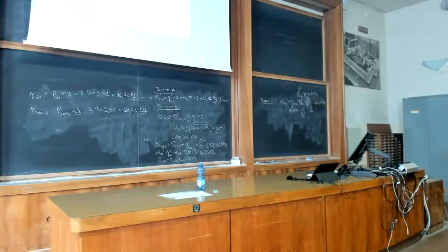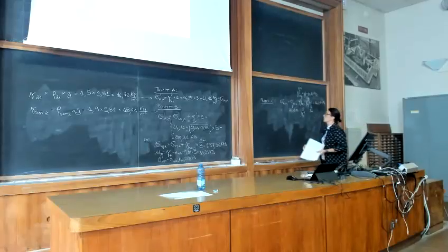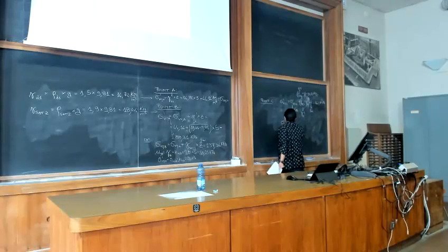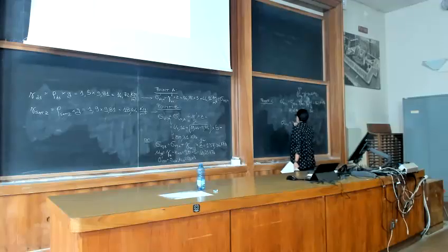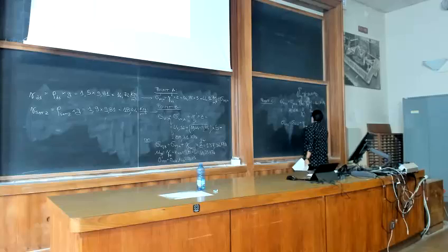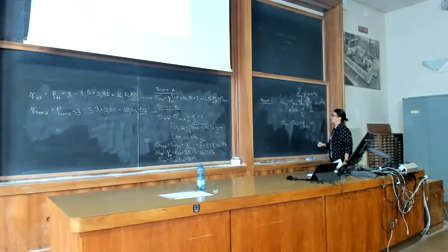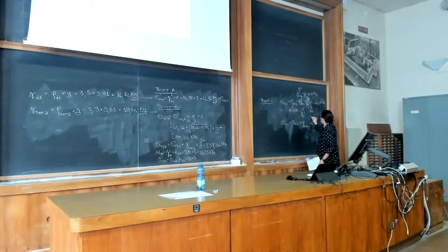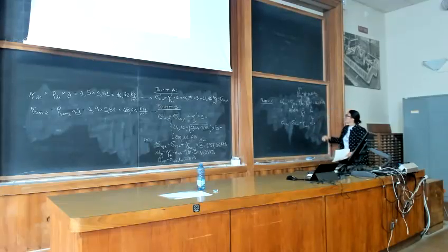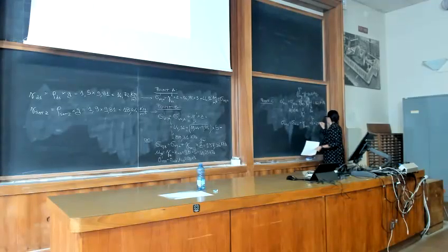If you need single values of total stress and pore pressure, you should add the calculation of sigma V naught in point C, which is sigma V naught in point B plus gamma sat of the third layer, which multiplies 8 meters. Okay, so in this case, you know everything. And you obtain 290.4 kPa.